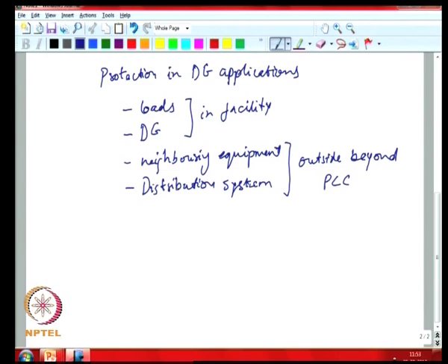You would have overlapping protection between zones and potentially backup protection in case something fails. Once you have protective relays, you need to think about their settings, and what sort of faults you are trying to protect against. Those aspects need to be decided.